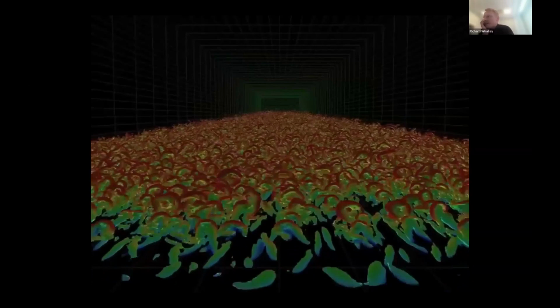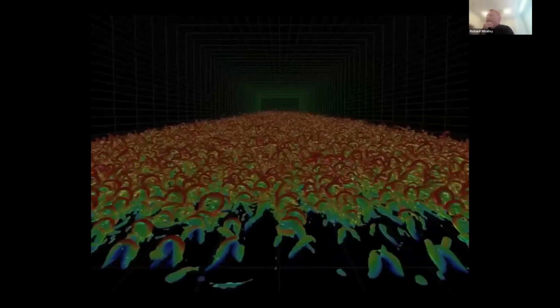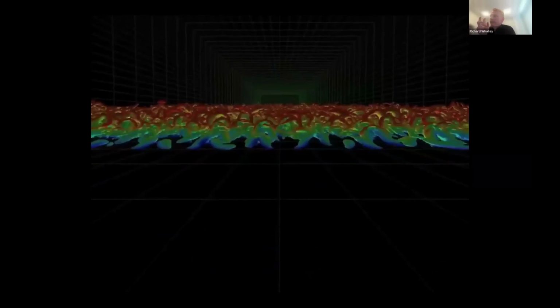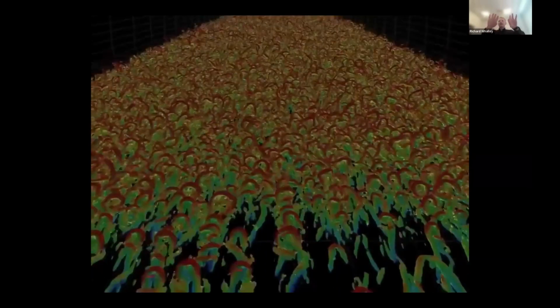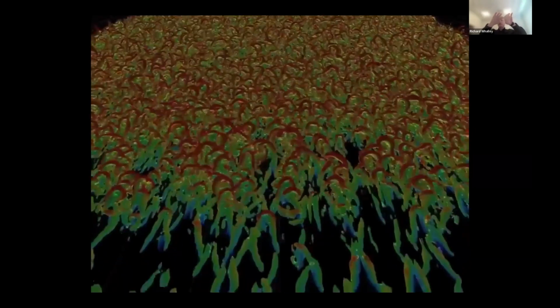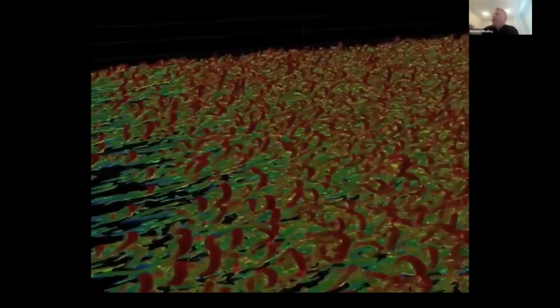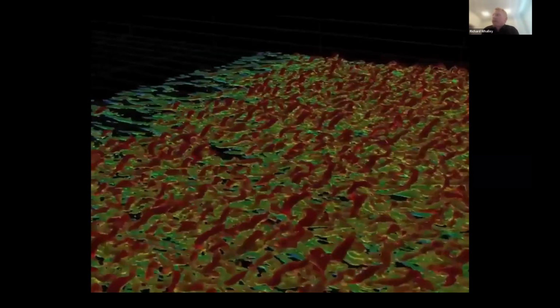So what you get is something like this. Flow is now going into the plane of the paper. When you go away on holiday and you're in your airplane, obviously you can't see the air, but there are all these turbulent structures. They look like little horseshoes moving along and down the flow. These horseshoes are quasi-streamwise vortices, which rotate like this, and they drag all the high-speed fluid from the outside of the aircraft in the free stream and crush it into the aircraft wall. It's that process, that downwash, that generates skin friction drag.